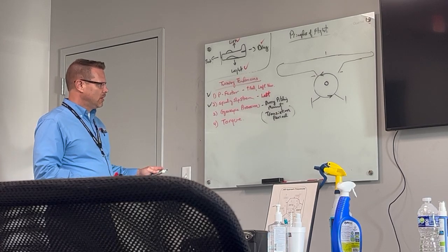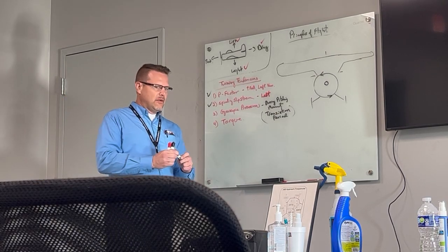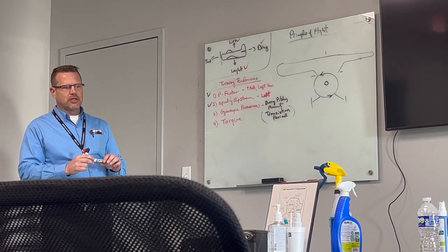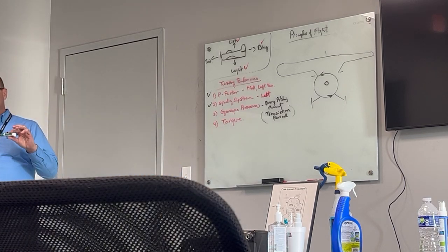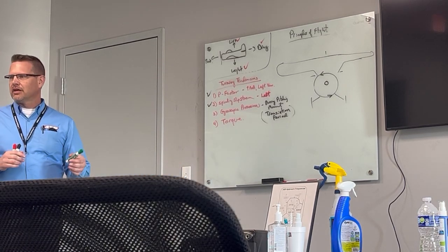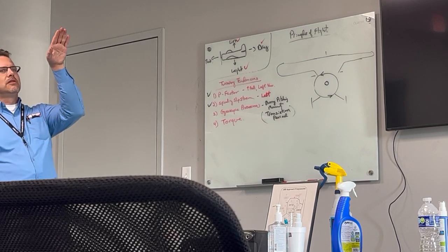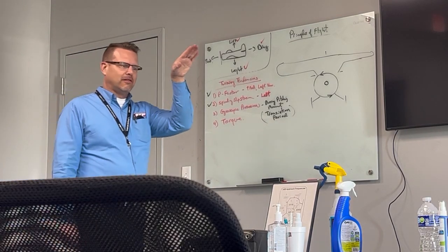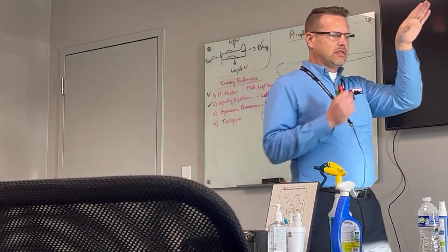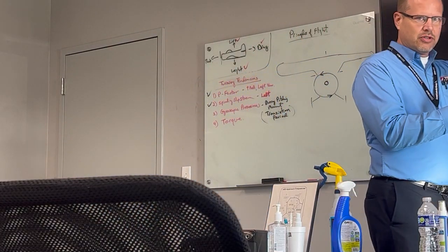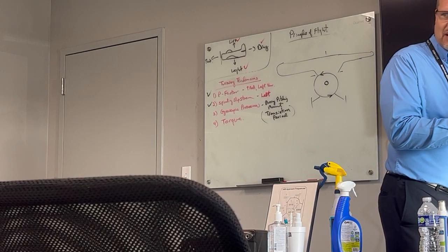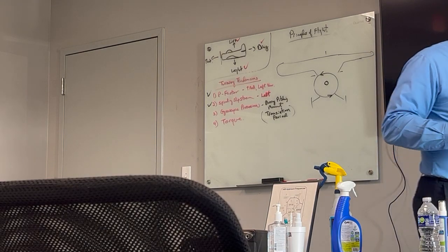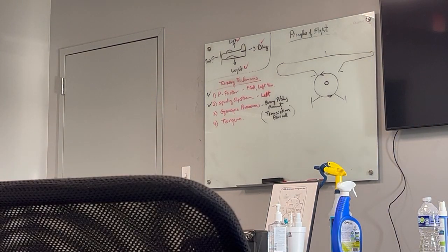So, if I was a tail dragger, the first thing a tail dragger needs to do is they need to pitch down, right? Because they're sitting like this, like a hoopty, right? You see those trucks going down the road, all jacked up in the front down here. And so the first thing they have to do is they actually have to push forward on the stick to get that tail wheel off so that they're just on the mains before then they lift off and they pull up, right?